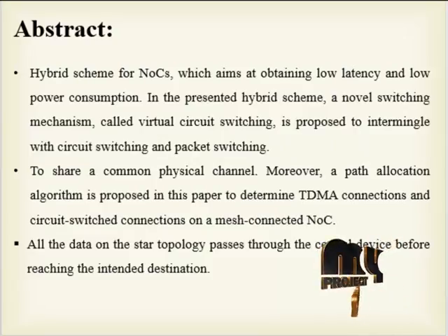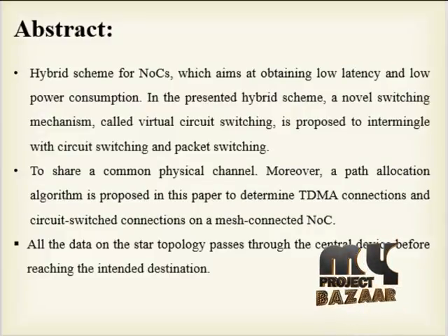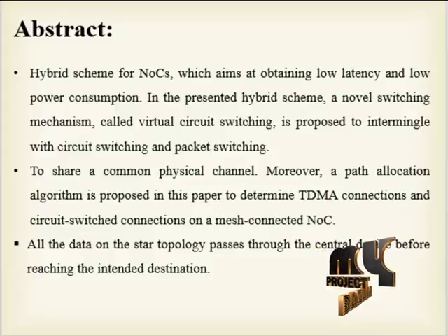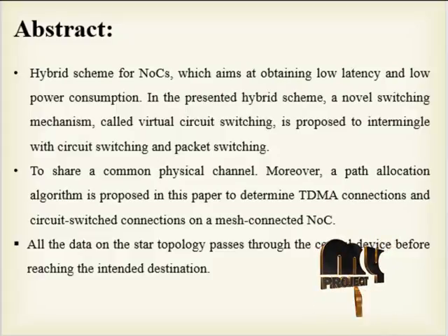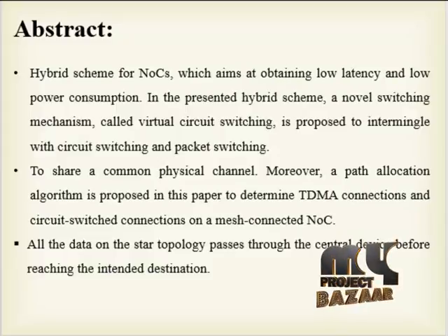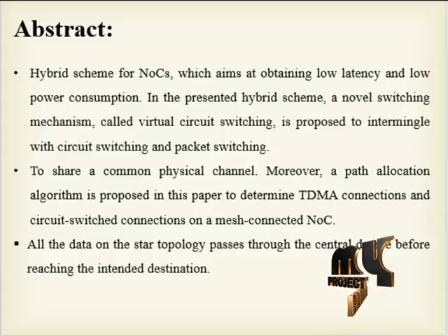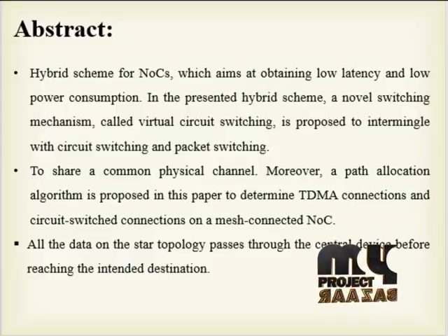The wireless 3D network on chip with inductive coupling through chip interfaces provides a large degree of flexibility for customizing the number of arbitrary chips in the package after chips have been fabricated. To simplify the vertical communication interfaces, static time division multiple access (TDMA) is used for vertical broadcast buses, while arbitrary and customized topologies can be used for the interchip network.